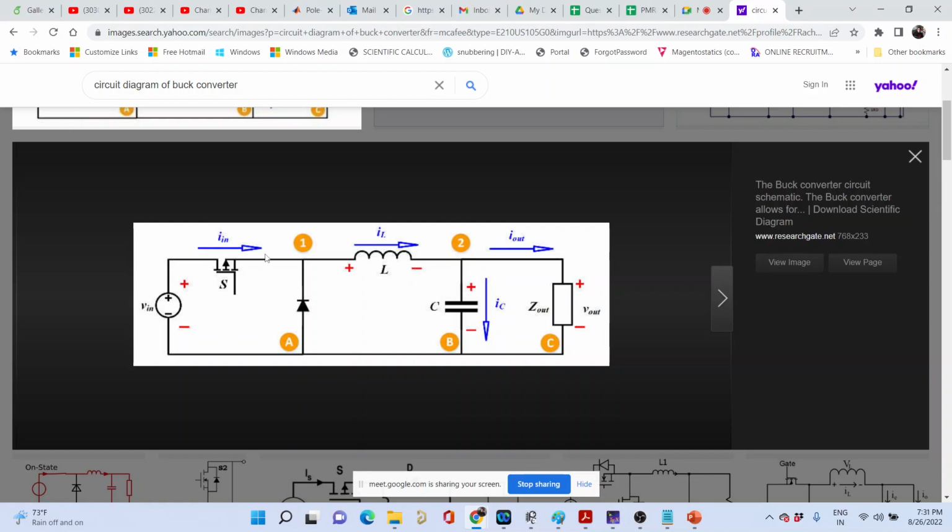Voltage control device, sir. Yes. So you need to connect a gate driver which can give you plus 15 volt or plus 10 volt or something, depending on what gate driver, what voltage your design is for. But with respect to whom? I am saying plus 10 volt. But with respect to whom do I need to provide this 10 volt? With respect to whom are you giving this gate pulse?